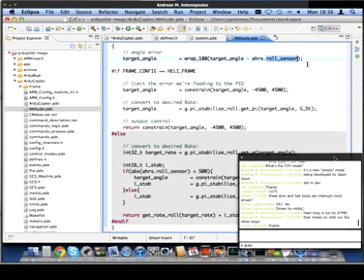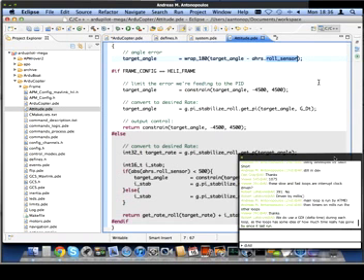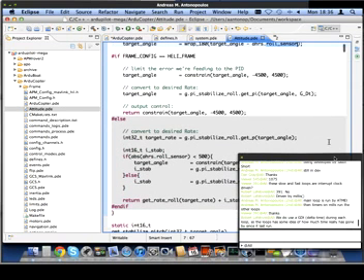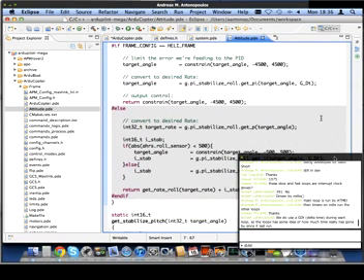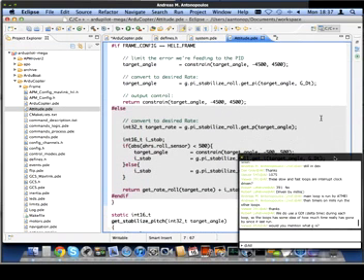It also compares that target angle being passed in with our current angle. That actually gives you the error, right? So say, for example, we're actually at 5 degrees now, but the pilot wants 20 degrees, so you'd come up with 15 degrees. Then we put some limits on it to make sure that it's not too big.